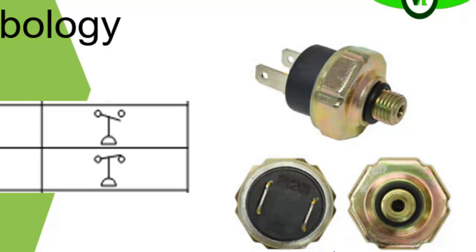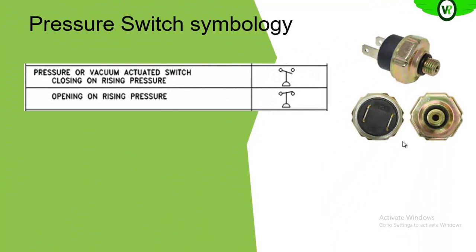So if it makes the contact, then if it is connected to a pilot light, it will indicate to us that the particular pressure level we set has been reached. If there is any action to be taken in the operational processes, then we need to take those actions to either bring the pressure down or maintain it at that level, not allowing it to go beyond that level. Or we can also configure it to control other processes.